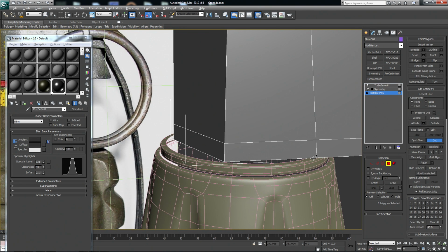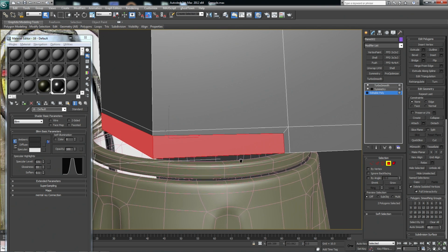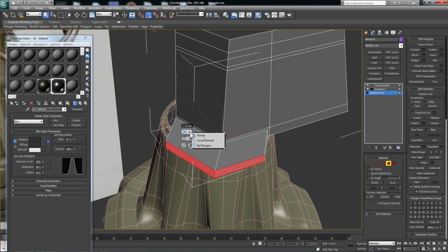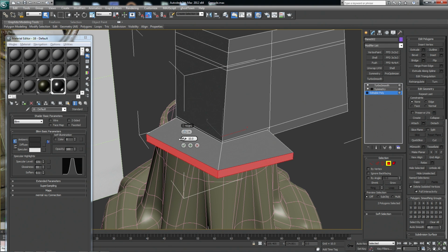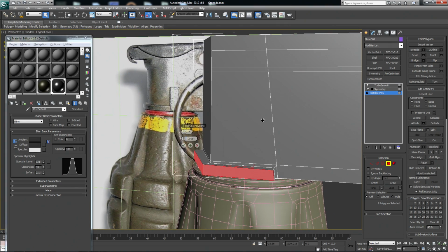Now before extruding out this front lip, I'm going to manually cut a border around so that when we smooth, the supporting edges terminate nicely. Now just select the faces and go into Extrude Options and Extrude by Local Normal. This way it flares out evenly and stays connected at the corner. You might as well toggle on the smoothing before you commit to make sure.